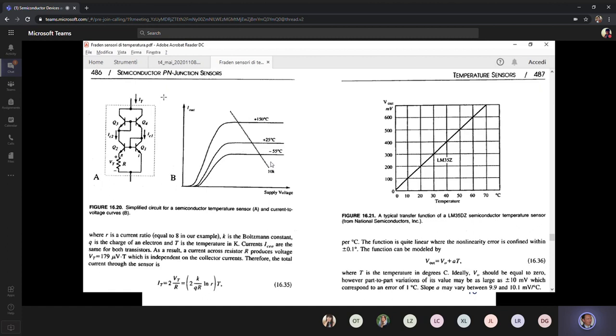That means that the two transistors on the upper level, Q3 and Q4, are able to force a given current into the lower transistors. That is, Q3 forces a current into Q2, and Q4 forces a current into Q1.